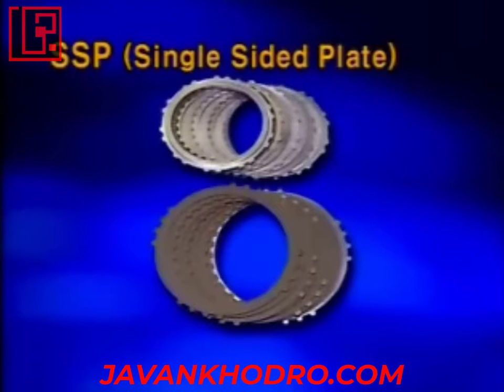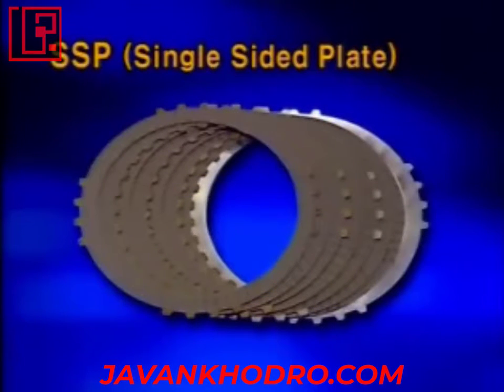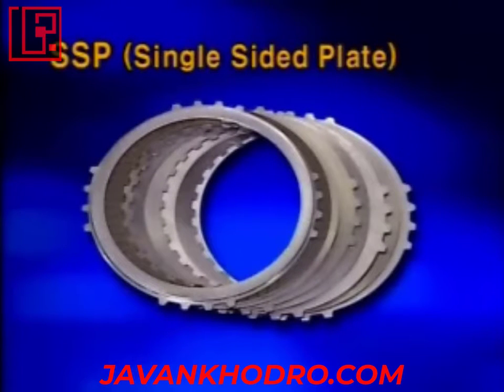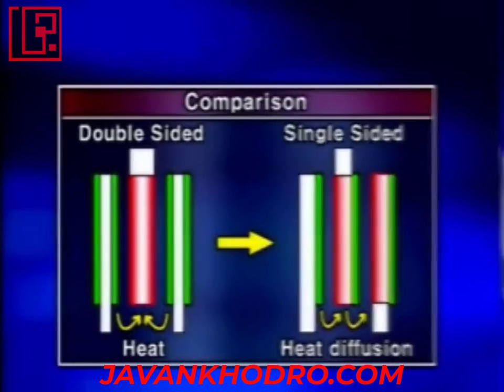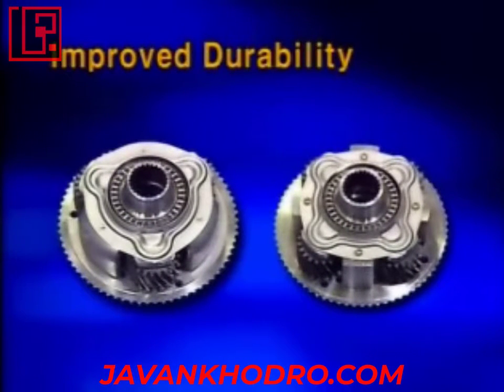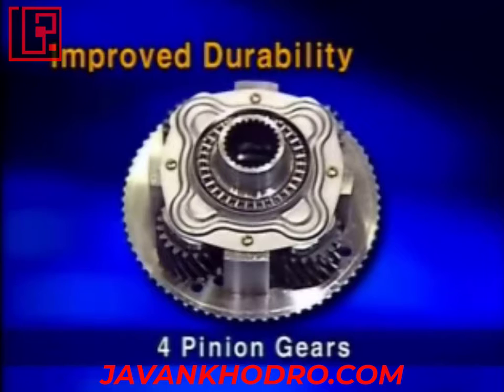Secondly, a new frictional material is applied to the overdrive clutch and the second brake. Conventionally, it is the double-side type. As the single-side type frictional plate is applied, the heat-absorbing capacity of the friction material can be enhanced, the durability is improved, and smoother shifting is obtained. Thirdly, the number of pinion gears for the overdrive and direct planetary carrier is increased to 4 from 3.